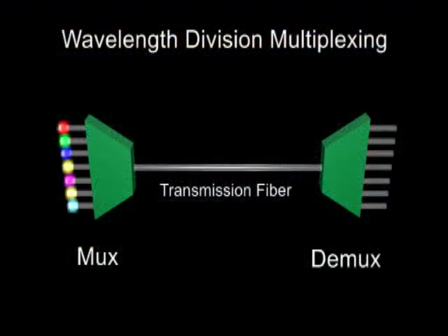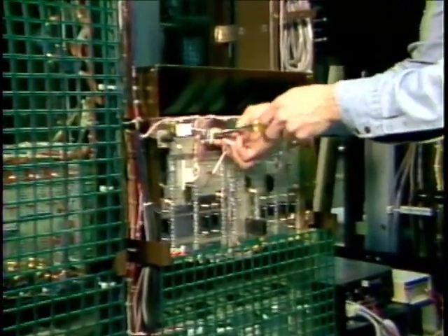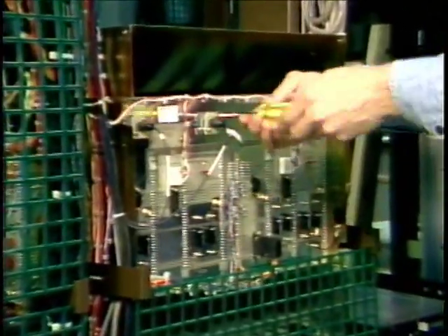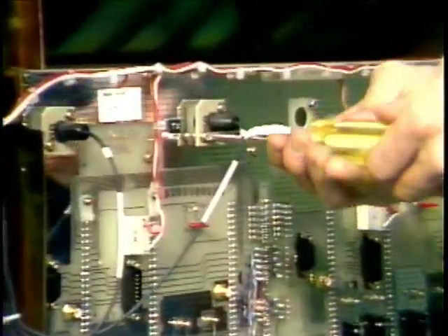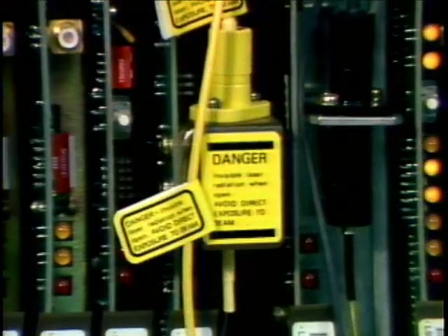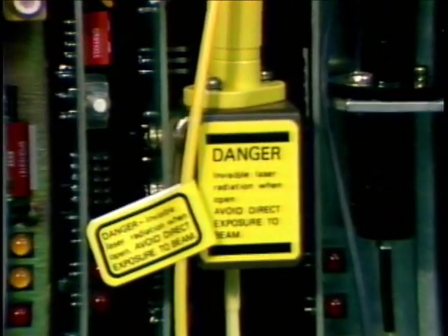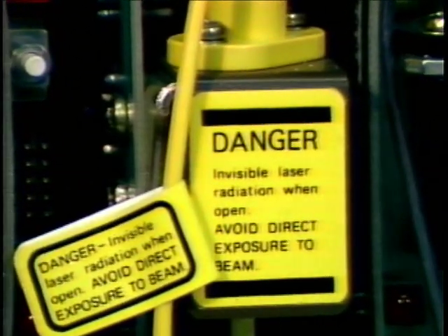Wavelength division multiplexing combines a number of optical channels into a transmitting fiber, with each channel transmitted at a different wavelength. Early terrestrial systems operated over multimode fibers with dual wavelength division multiplexing, or WDM, at 850 and 1300 nanometers, using wide spectral width LEDs. Later, these systems migrated to single-mode fibers, using laser sources operating at 1310 and 1550 nanometers.